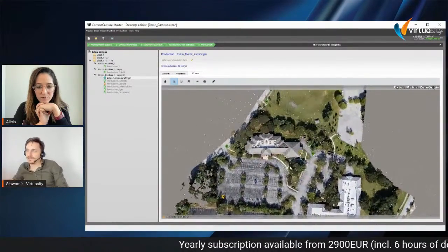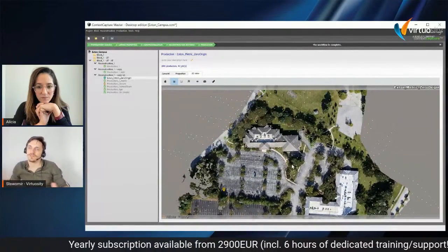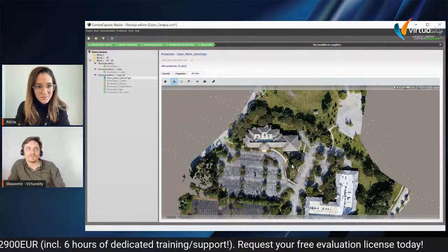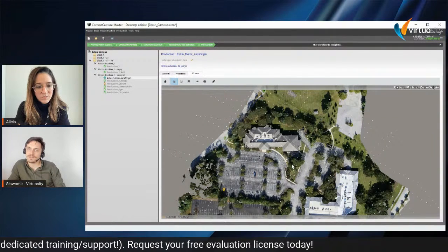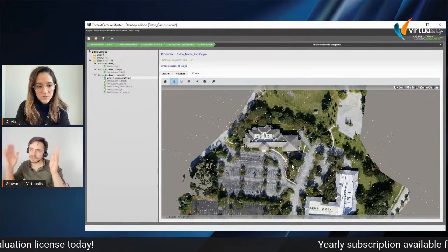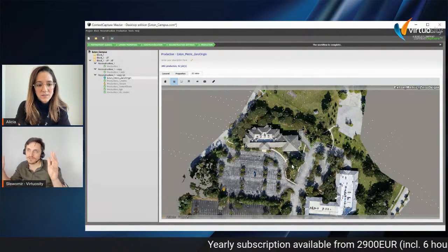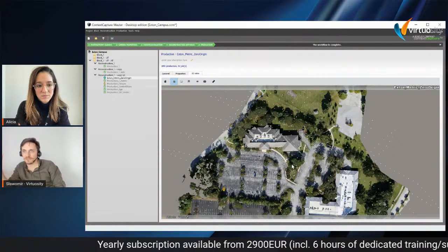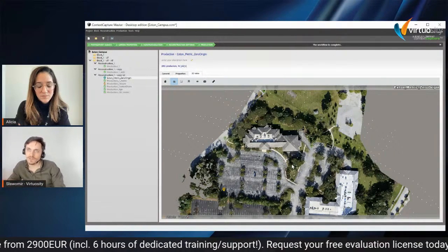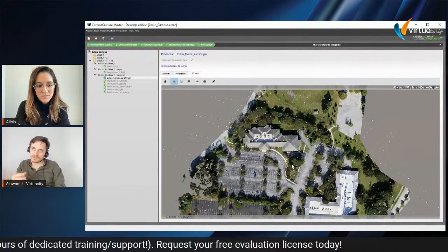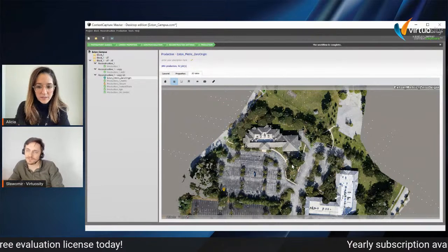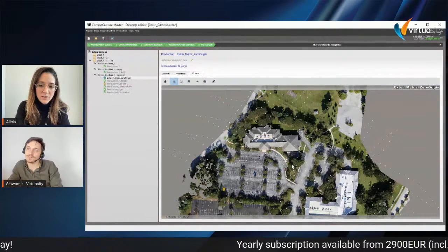Basically, the reason to use those local, small coordinates is that some BIM software and some CAD software have an issue processing huge coordinate numbers, which have 7, 8, 9 digits. That's a lot. By shifting everything by a vector, like 2 million, 1 million north, 1 million east, for example, we are just lowering those numbers to a 3-digit number. And it's much easier, especially since projects are mostly done in local coordinates.